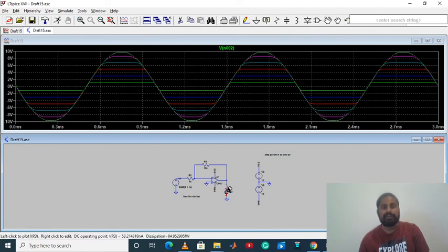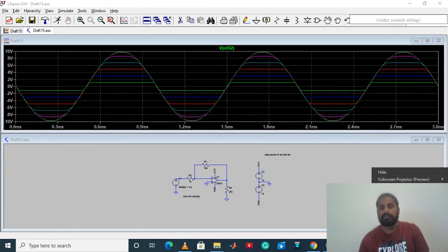So by this method we find the output resistance of the op-amp, and if we connect a load of less than 130 ohm, our output will decrease. So this was all about how to calculate the output resistance of an op-amp.